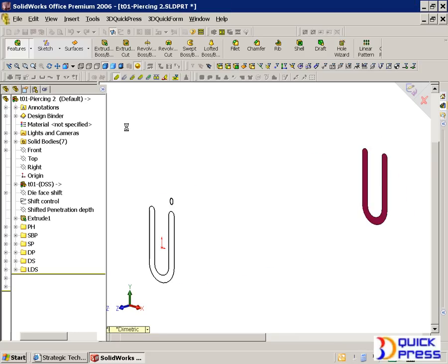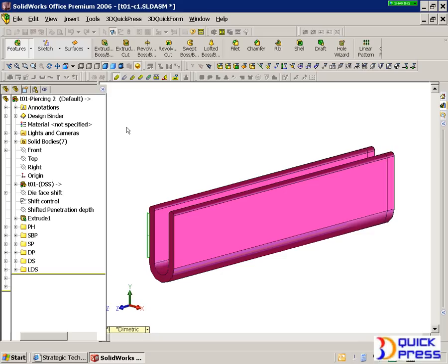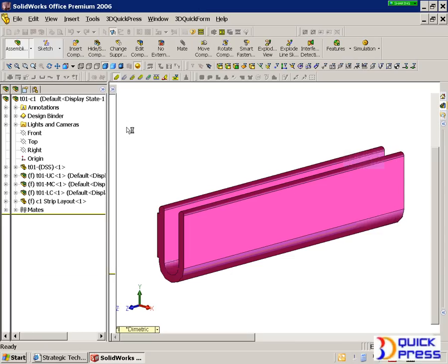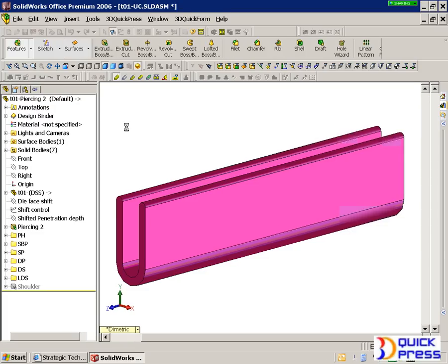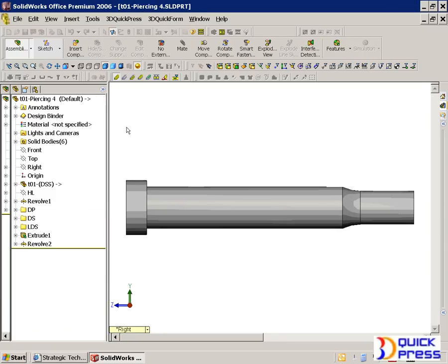That check for whether it's unique or not doesn't only work for purchase punches, it also works for totally custom punches. So you can see there are different shapes on here. Let's say it was some kind of U shape that was used in 5 different areas. The punch will only be created once, one ID, one part number, but it will be instanced 5 times. We figure that out. Other CAD systems are going to create 5 different part numbers even though it's the same punch. Talk about confusing people downstream.